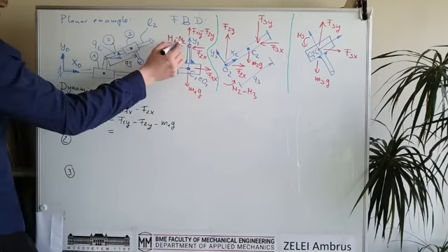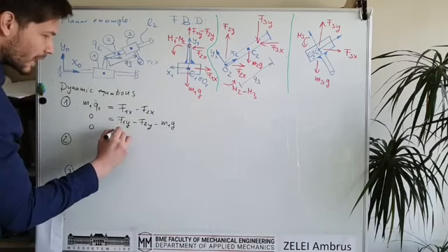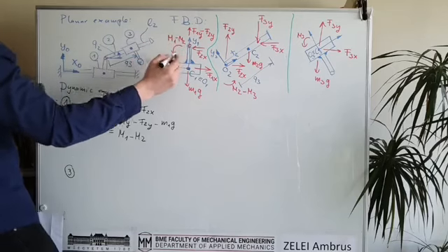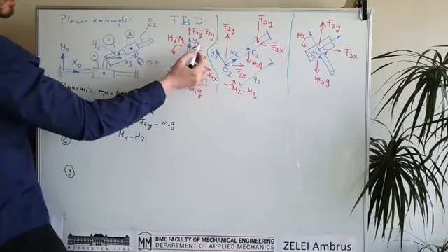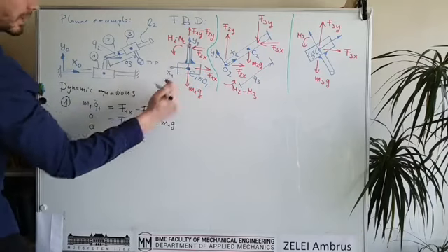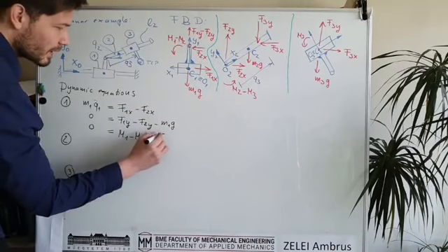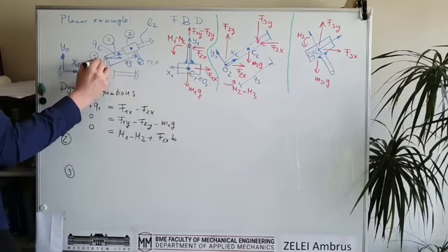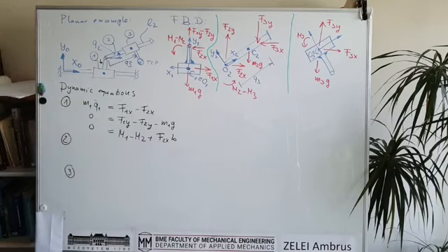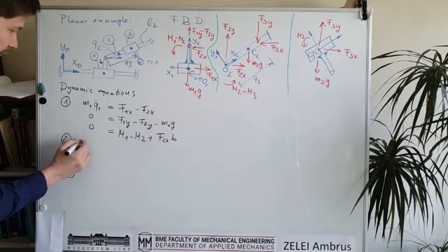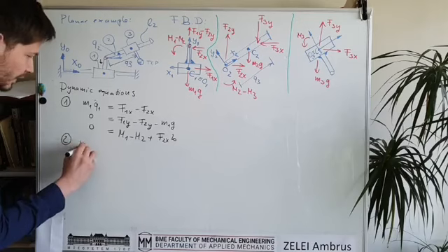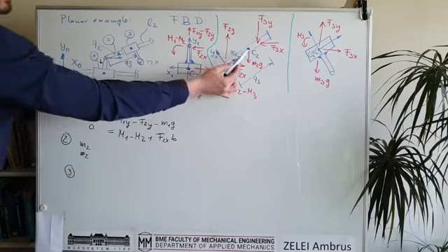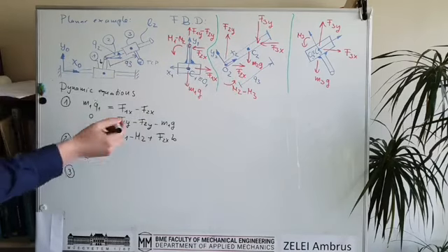It's very important. We are calculating the sum of the torques acting on the center of mass. So we have positive m1 minus m2, and we also have the moment of f2x, which is positive. So this is f2x times parameter b, which is measured here. So this is the set of equations for the first rigid body, and then we have the set of equations for the second rigid body, of which the center of mass moves in a general way.